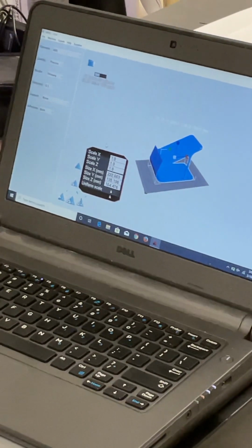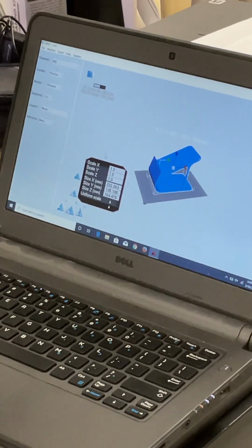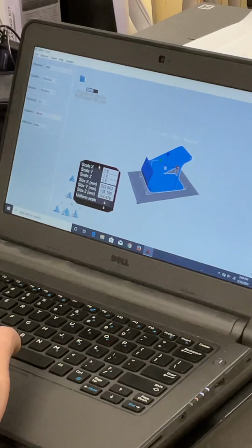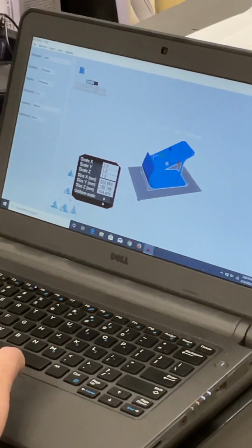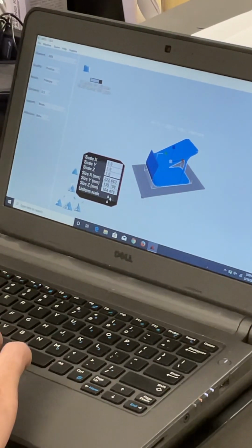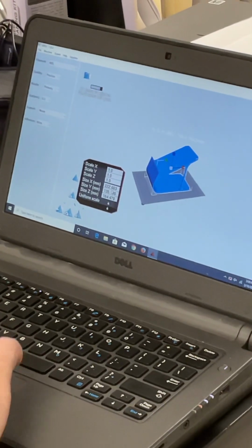This one is a little tricky, okay? This is where you can change the size of your objects, but it's a little tricky to enter the actual size you want. So what's going on here, you have a scale X, scale Y, scale Z, okay? You want them to be uniform, which means you want them to be the same, okay? So keep this uniform scale lock locked. Keep the major lock locked, okay?